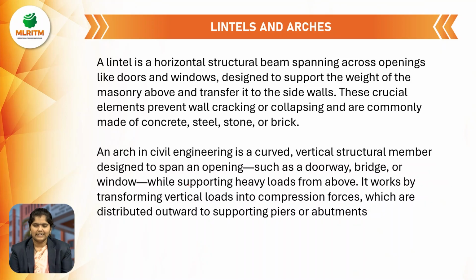And next, lintels and arches. A lintel is a horizontal structural beam spanning across an opening like doors and windows, designed to support the weight of the masonry above and transfer it to the side walls. These crucial elements prevent wall cracking or collapsing and are commonly made of concrete, steel, stone, or brick.